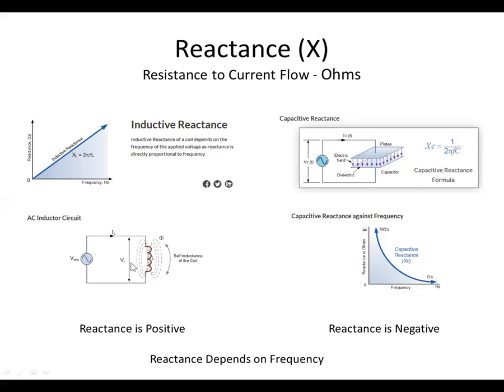And that's what these dashed lines are representing, is that as the current flows, a magnetic field is generated and surrounds that inductor. And then when the voltage switches for the second half of the cycle, that magnetic field collapses and is built back up in the other pole direction.